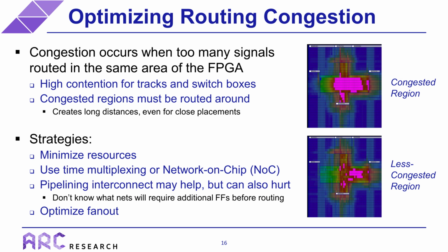Another potential solution is to use pipelining again, because you could pipeline the signals that get routed around the congestion, but we have the same limitations that we saw before. A lengthy path in one compile that we pipeline might just get replaced by another lengthy path in another compile. So this pipelining strategy might just be shifting around the bottleneck on each compilation. Also, the addition of these extra flip-flop resources to an already congested design could potentially worsen the congestion and outweigh the pipelining benefits. Very often, routing congestion is caused by high fan-out signals, especially wide ones.